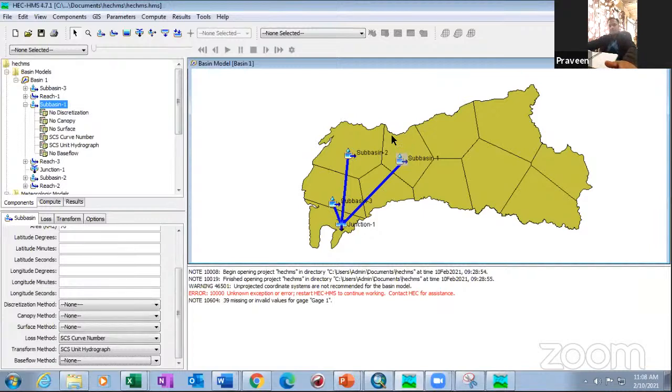Why? Because when there is base flow, the time taken for the infiltrated water to reach the outlet will be a lot, right? So within that time, your simulation time will be over, and adding it will make no sense. But if you are modeling a long period, like 2-3 years or 10 years, then base flow is important, and you can define the base flow using monthly averages or the different methods available.